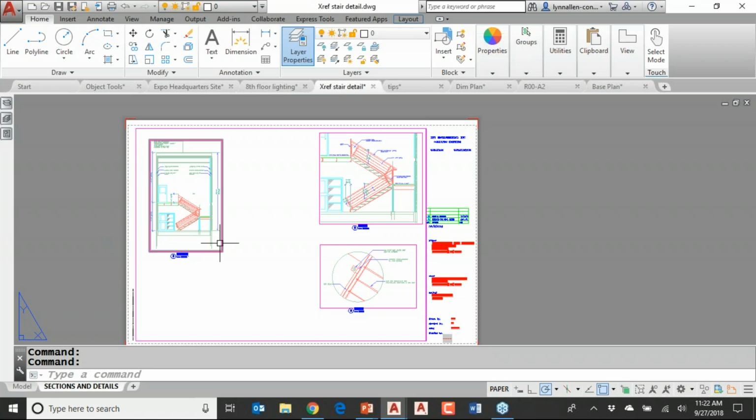We're kind of back to our issue before, right? That ByLayer issue. Well, that's frustrating. Now, I don't really want to go back to that source drawing and start making changes, or somebody might get mad at me. But there is a super, super awesome system variable that allows us to override that awful ByLayer issue. If I type in XREFOVERRIDE and set that to 1, watch the screen, you will see that I was able to override all those settings that are not ByLayer. And look, now it played by the rules. Now everything is that funky green color that I set it to.